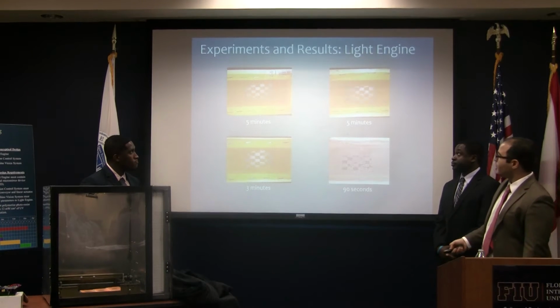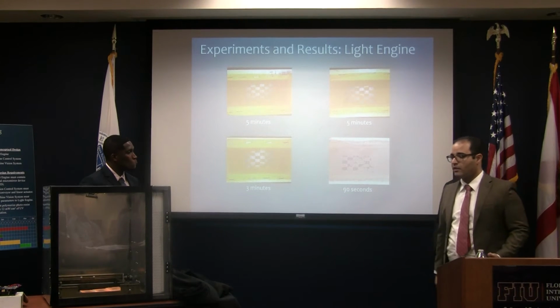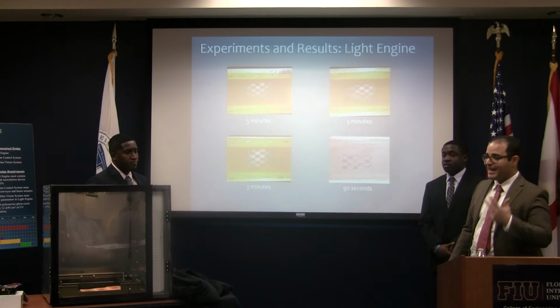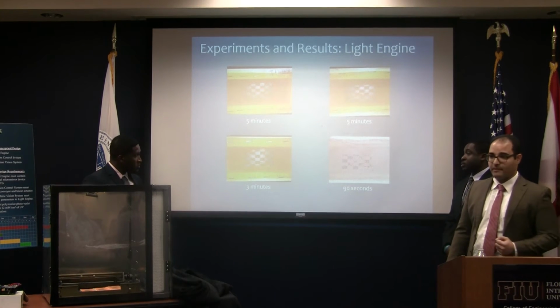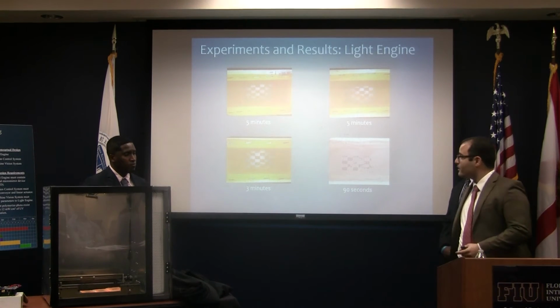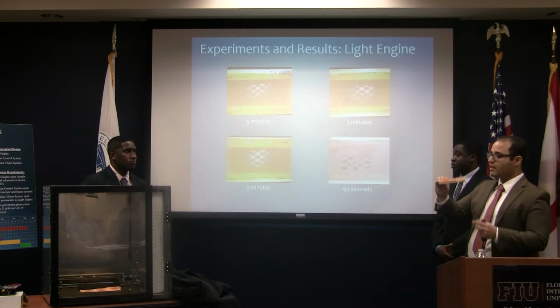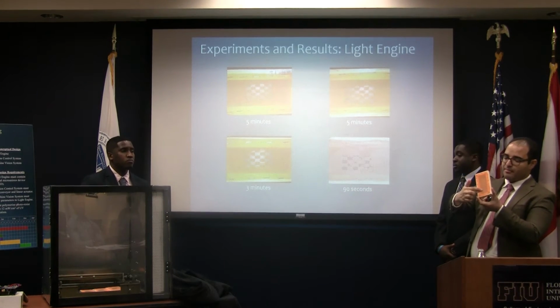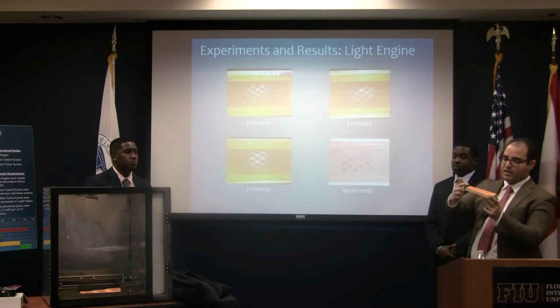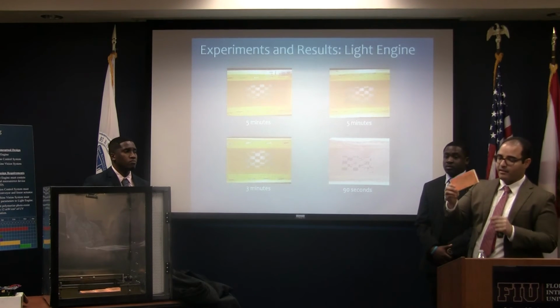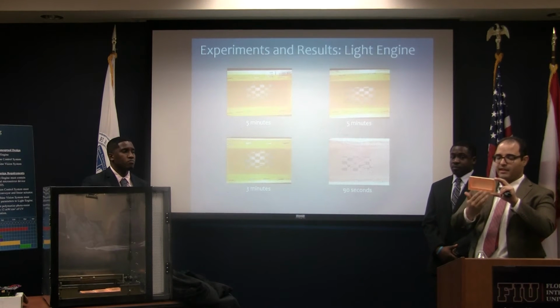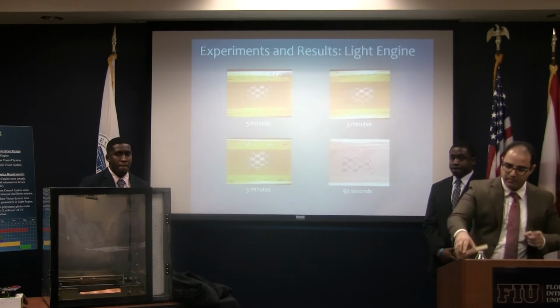So our next test, we just wanted to see if it can expose an image onto the photoresist. So what we did is we constructed a bunch of wooden frames measuring 6 by 3 inches, and we stretched this screen printing mesh and we stapled it onto that. Afterwards, we applied the photoresistive material.